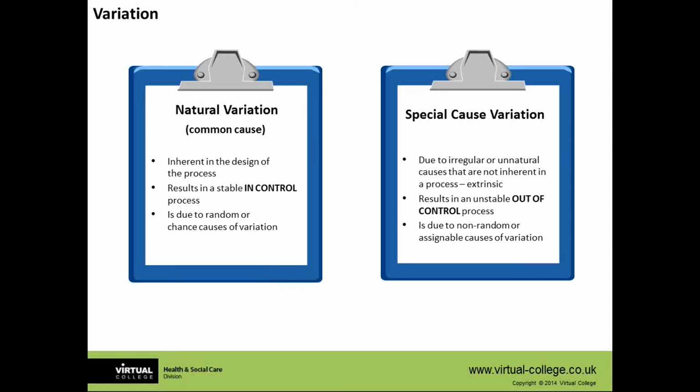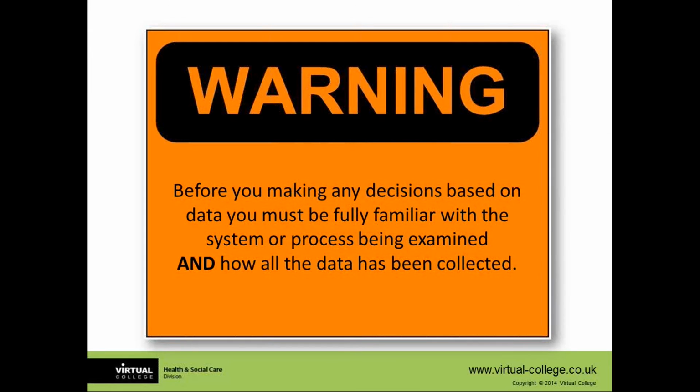But building on the 7 quality tools, these are tools that can enable you to look, plan, understand and manage your process or your service going forward. So they're very useful. Okay, so it enables you to pick out variation. So once you've worked out your upper and lower controls, you'll have a natural variation. And basically, if nothing changes, the process should sit within its limits 99.7% of the time.